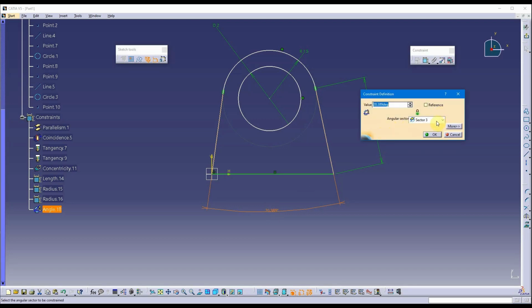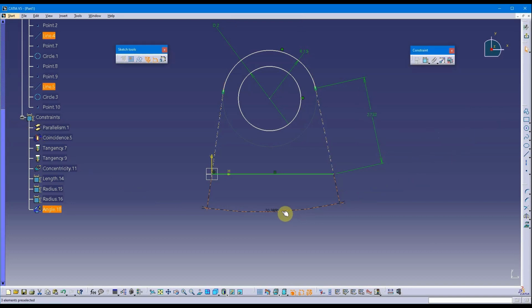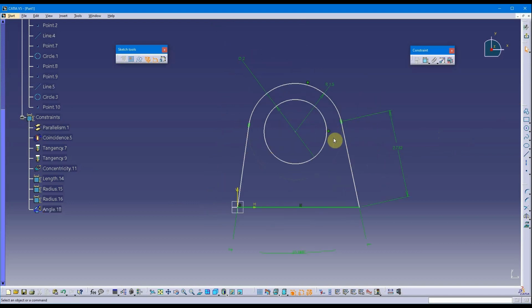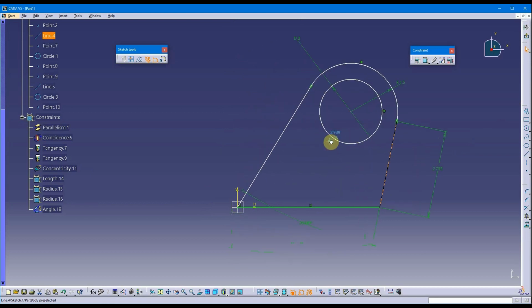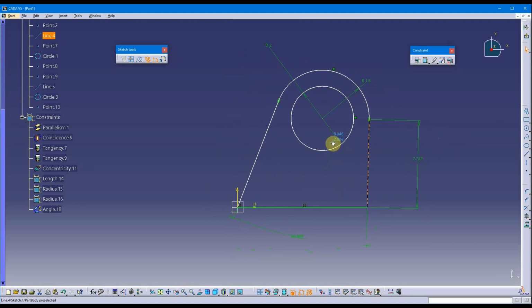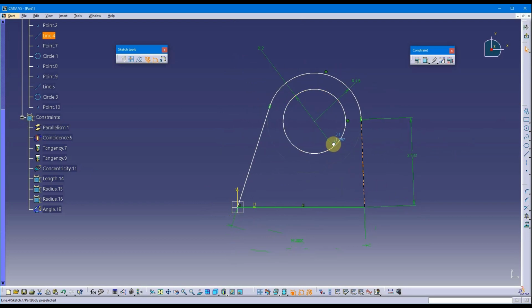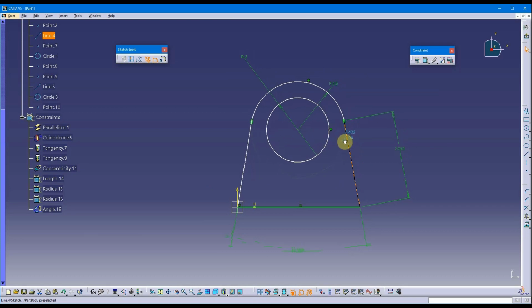And you can actually change the sectors, how that's going to be displayed. I want to leave it at sector 3. Now, there's my angle, but notice I'm still white here, which white is bad. So why am I white? Well, what I recommend doing is just trying to move your white geometry to see where you're not constrained. I've got that angle in there, but I'm missing symmetry.